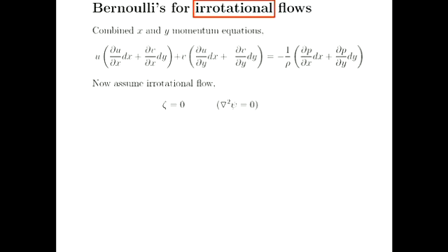Do you remember the two velocity gradients that were involved in vorticity? It was du/dy and dv/dx, right? So vorticity equals 0 implies that du/dy must equal dv/dx, because vorticity is just dv/dx minus du/dy, okay? So if we've got 0 vorticity, I know that condition is met.